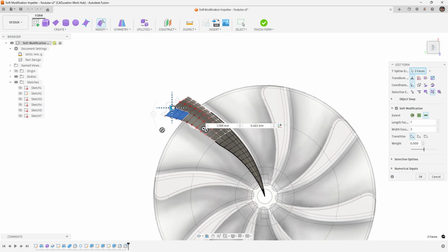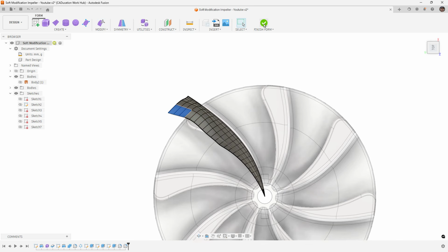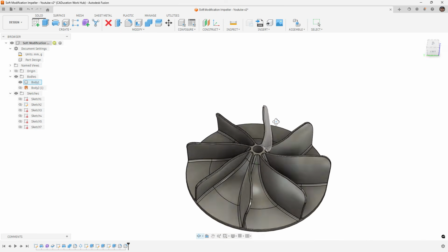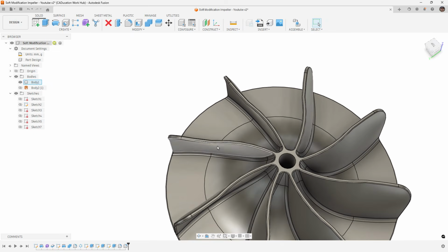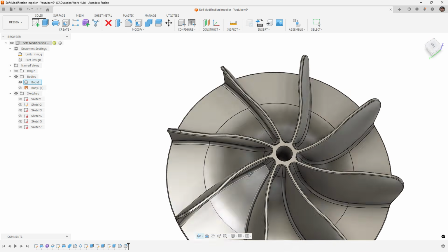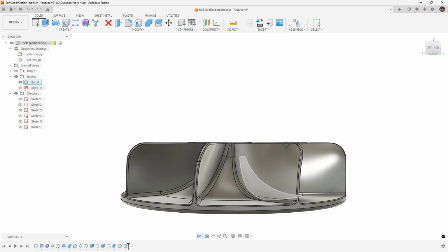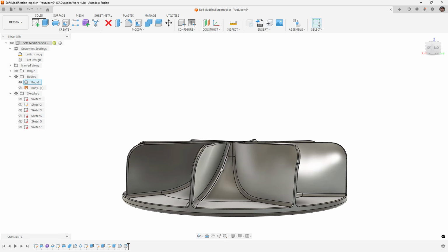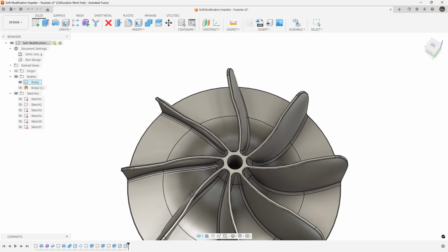And I'm going to sort of pull this back so there's this little bit of a hook in the shape. We'll say OK. We'll finish the form. We'll allow it to regenerate. Again, it's got to go through the process of thickening. You can see we've got that little bit of a hook, that step in the form. And because it was trimmed away, it's not nearly as drastic as where we actually adjusted it, but you can see that there is very clearly a change there.